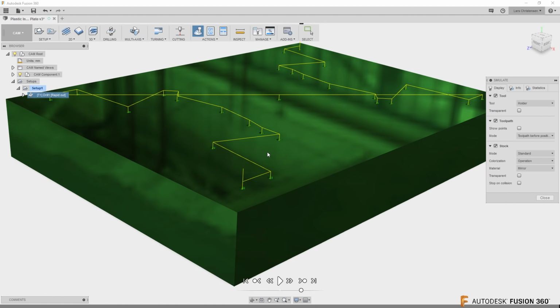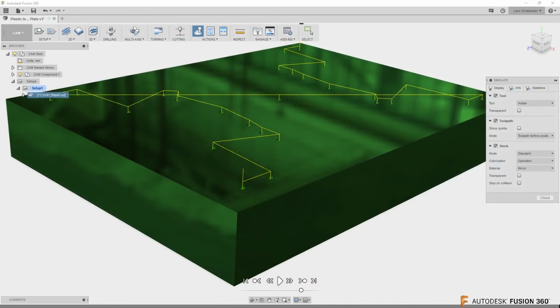So actually, the spot drills I have always used are what I think are called spot mills. So it's a 90-degree cutter, but you can actually chamfer with it too. So it's kind of like a 2-in-1 tool. You can spot with it, and then you can chamfer with it too. Spot mill, I think, is what I always called them when I called up to order. So search for those. So this is pretty good. I'm pretty happy with this here.